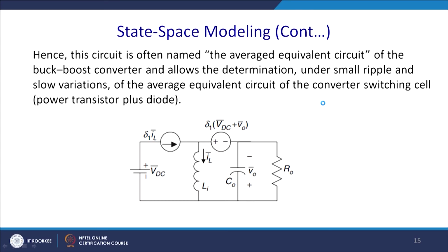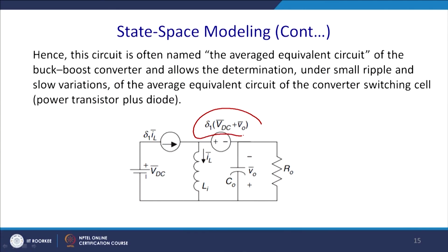So, let us see. One observation we got from the state space is what should be the desirable frequency and whether you are well above it or not. Now, another way to analyze the state space, once you already have it, because it is a set of differential equations written in matrix form, is a very simple thing to do for many of us. So, what happens if you give some disturbance across the average value?